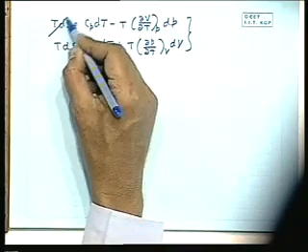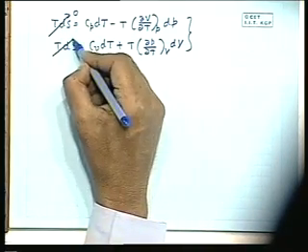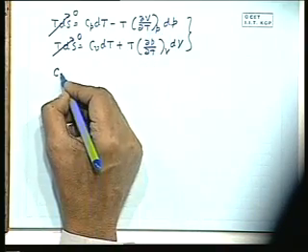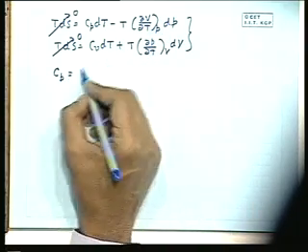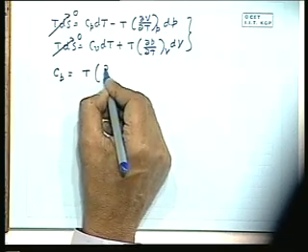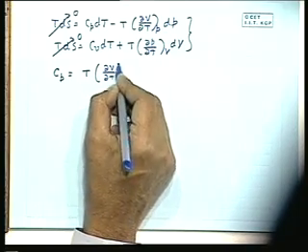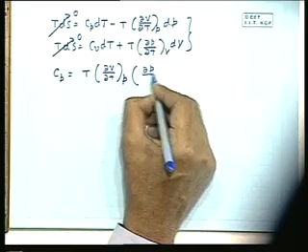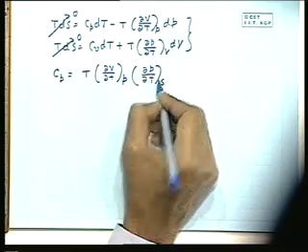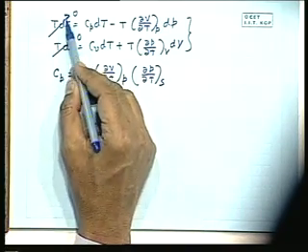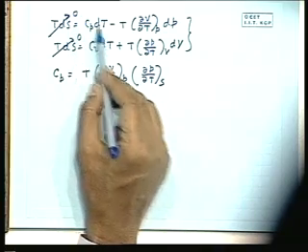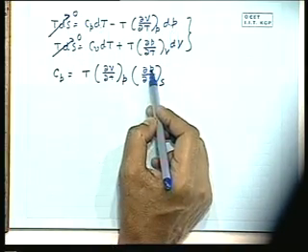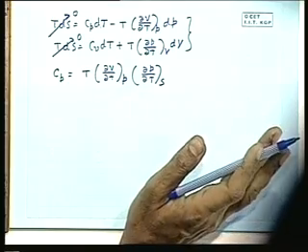Now if we consider an isentropic process, dS is 0, from here what do we get? We get Cp is equal to T del V del T at P, and this dP, then that will be del P del T at constant S, because I am using the constant entropy TDS, then this becomes 0. So dP by dT at constant S will be defined as del P del T S. This is clear?